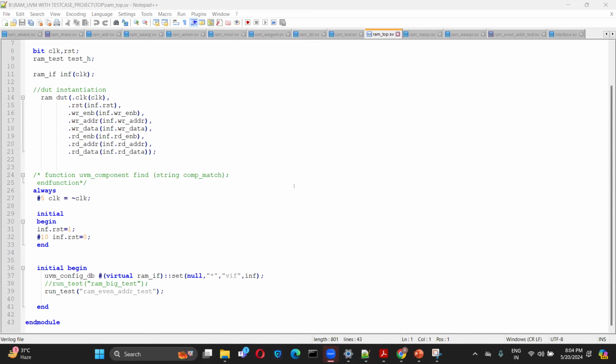Fine. So this is all about the virtual interface, and we have also gone through the APB protocol specification today: what the APB protocol is, how we decide which protocol has to be chosen, and the advantages other protocols have which are not present in the APB protocol. We also discussed the different features, like wait states in APB, how it works without wait states, and the significance of the PSEL, PENABLE and PWRITE signals.